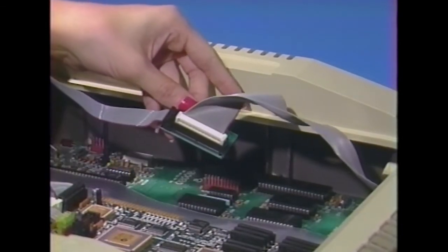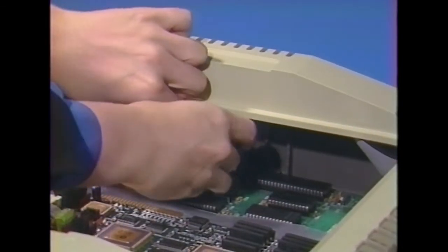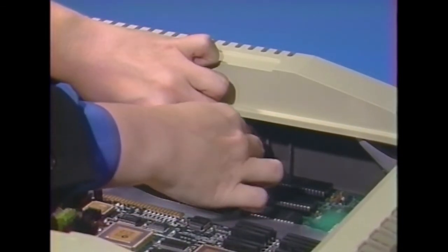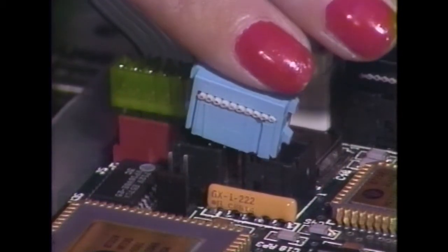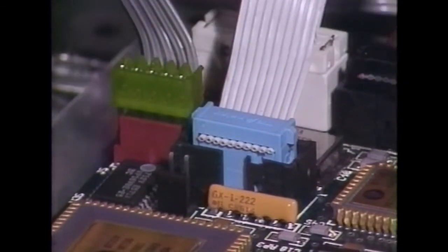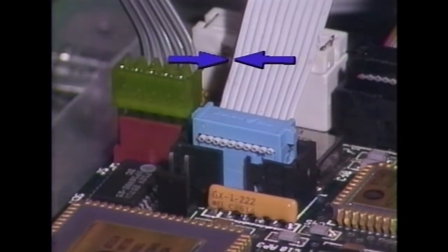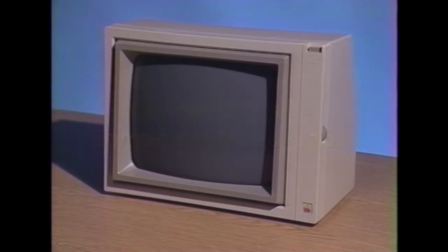Connect the IIe keyboard adapter card to the IIe's motherboard at location J1. The 10-wire cable should be leading away from the board toward the computer's backplane. Now connect the male 10-pin connector from the adapter card to the female 10-pin connector on the transporter as shown here. Again, the stripe on the cable must be toward the top edge of the PC transporter. If you are using an Apple-compatible composite monitor, follow these steps.